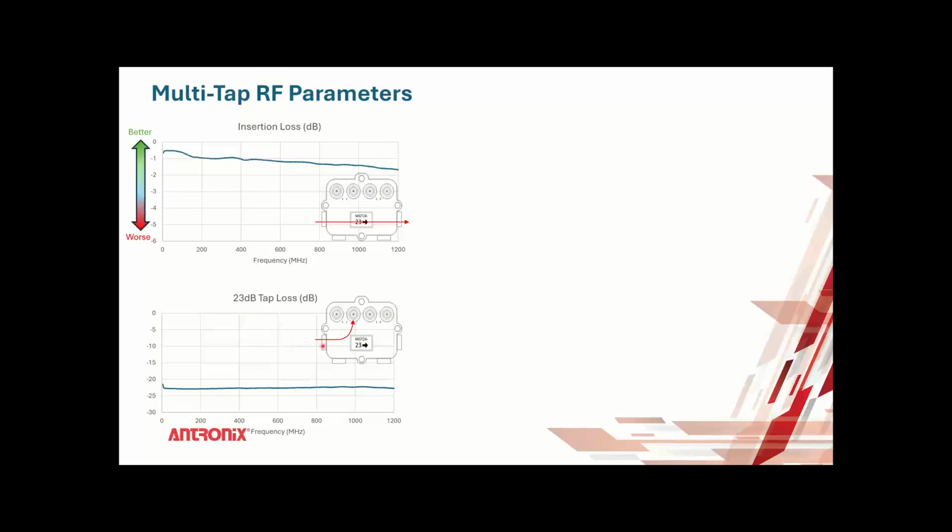And as we mentioned before, on a 23 dB tap, going in through the F port, this is called tap loss. So the loss between the input of the tap and the F connector determines your tap value. And there's 23 across the board in the frequency response I can see here.